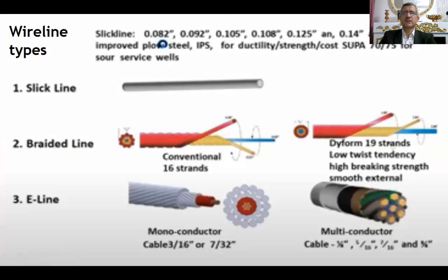After that, it will not be used anymore. We then have to use the stainless steel. Stainless steel is more resistant to the corrosion of H2S, of CO2, or any similar environment, but it has less tensile strength. So every type has its own uses.